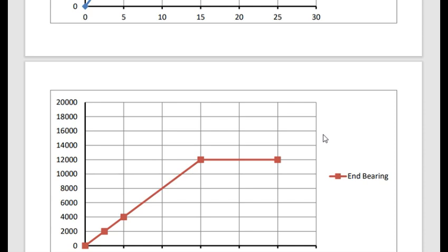So end bearing is the easy load, so it can carry more. This is usually, but it depends on the layers. Suppose that you have very good layers all around the pile, and at the bottom you have very soft layer. So the end bearing will be nothing, but the main force will be what is all around.